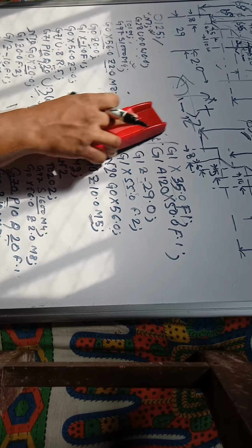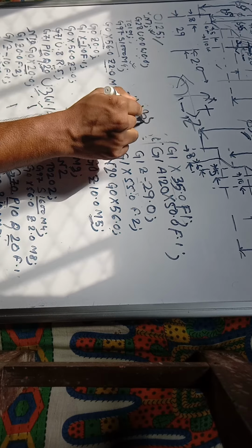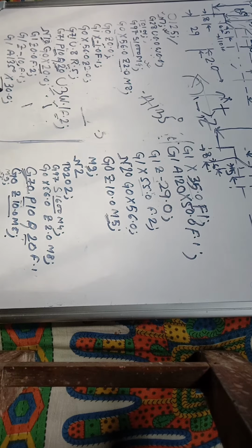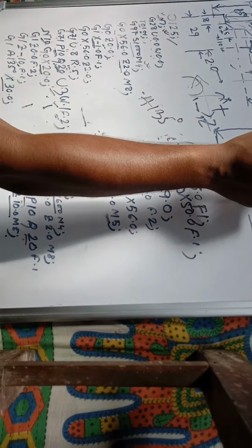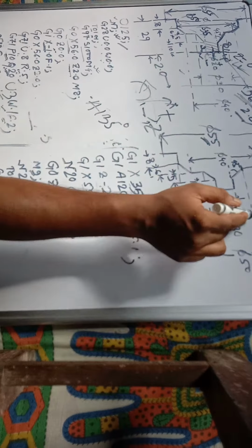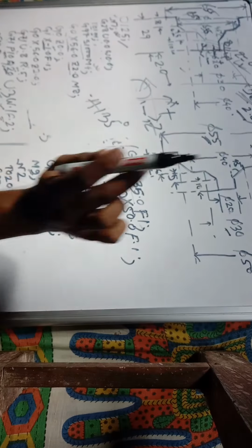So what is the angle value? It will be simply 135 degree, 90 plus 45 degree, and it will move upward to X30.0. So it will reach here, that is a point of X 30, and the angle is 135 degree.